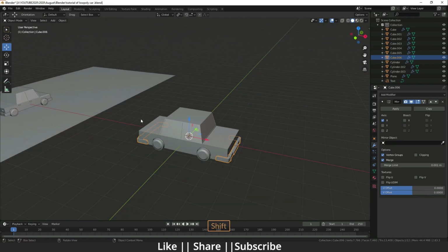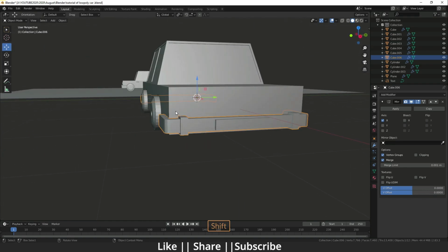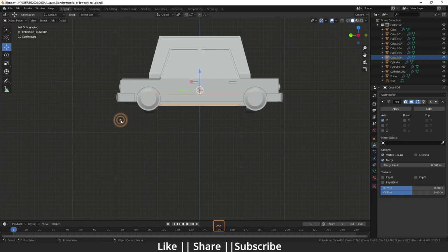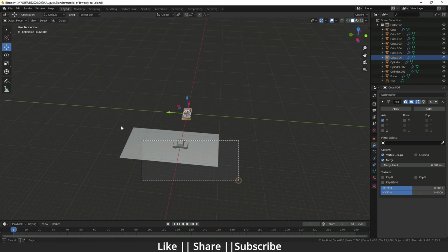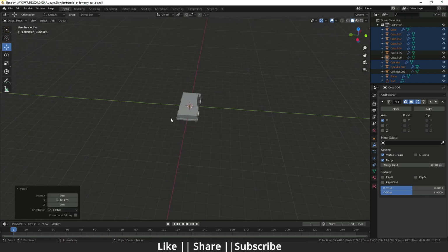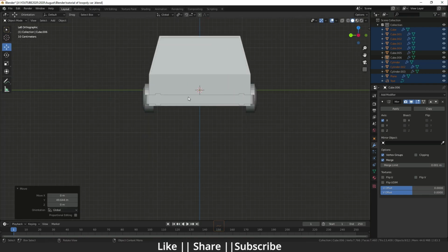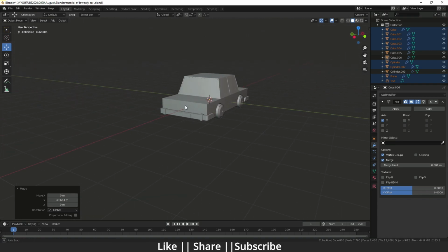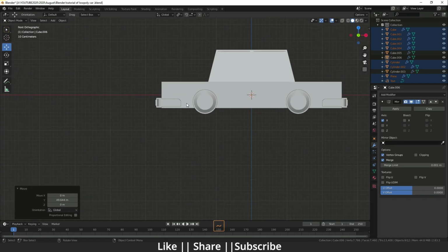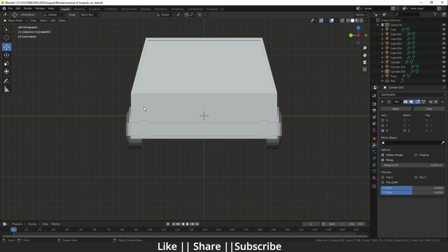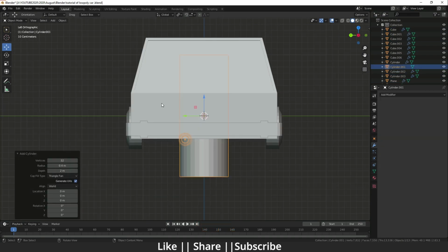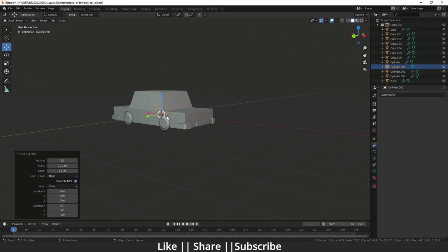So now we have to make a headlight here. For that, first of all, I'm just going to drag it like that. I'm going to front view. Okay, I think that is the front view. Yeah, front view. So now I'm just going to add a cylinder, and I'm just going to set n-gon and align to view. I'm just going to increase the depth as well as the radius like that.